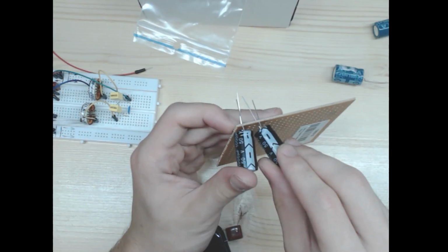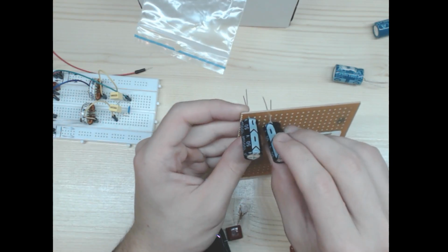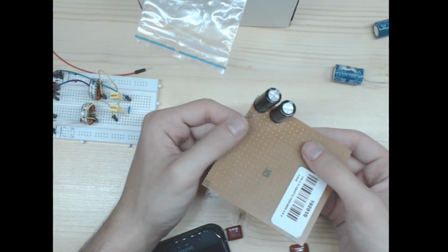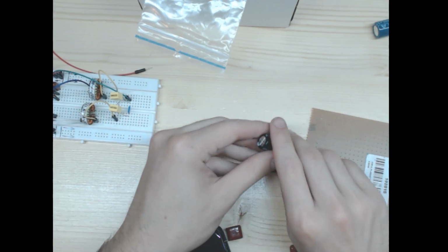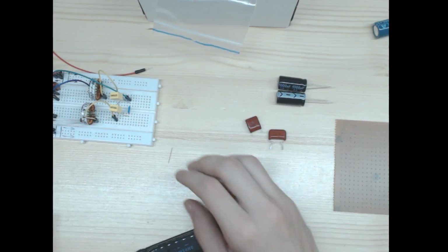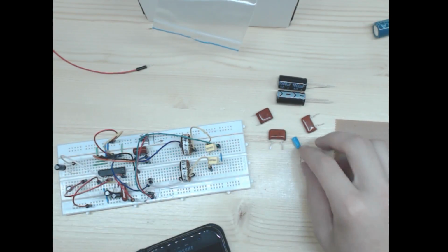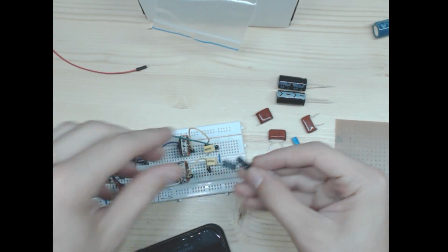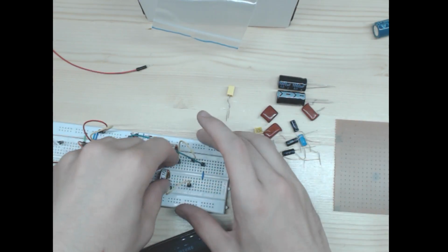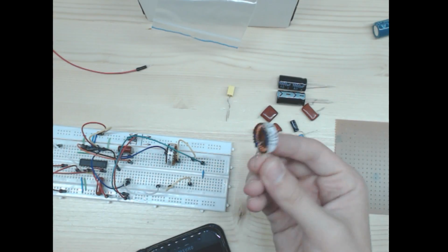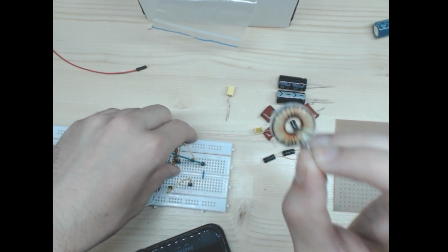Quite beneficial, in fact. I mean, we can separate it a little more. Already, it's a lot better. So we'll try using these. We need these. We need this. We need a 10 microfarad electrolytic. We need some 1 microfarads for inputs. We need these ceramic 0.68 micro. We need these nice power inductors at 33 microhenry.